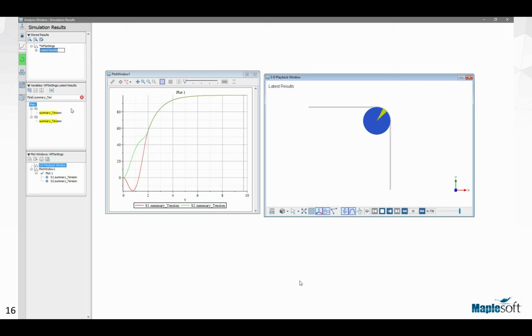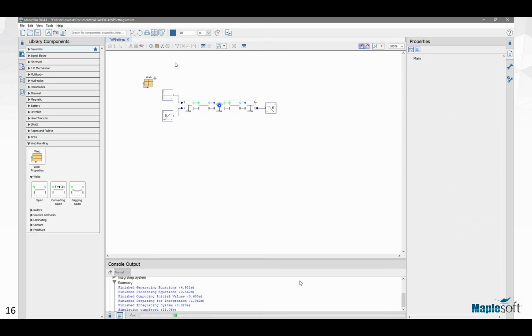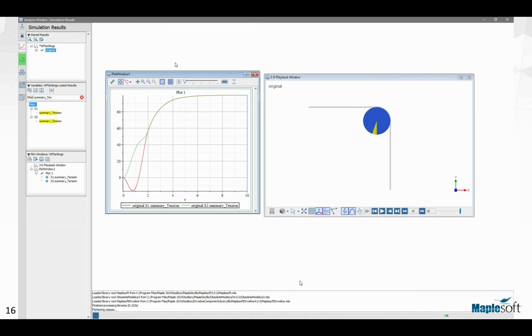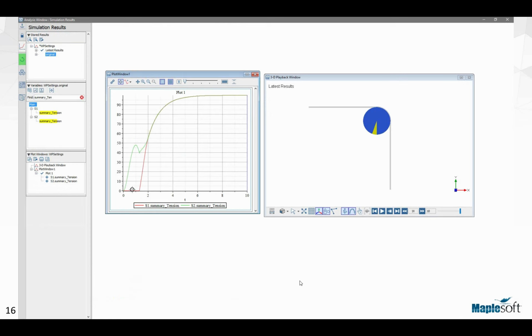This type of situation is usually something that one can ignore and continue the simulation once the steady state is achieved. But in certain cases where we want to look at it and treat this negative tension as potential accumulation of material without really paying the price for sagging or any other feature, we can activate the prevent negative tension. As you can see, this time when the tension is negative, the material is assumed to accumulate in span 1 at 0 tension.